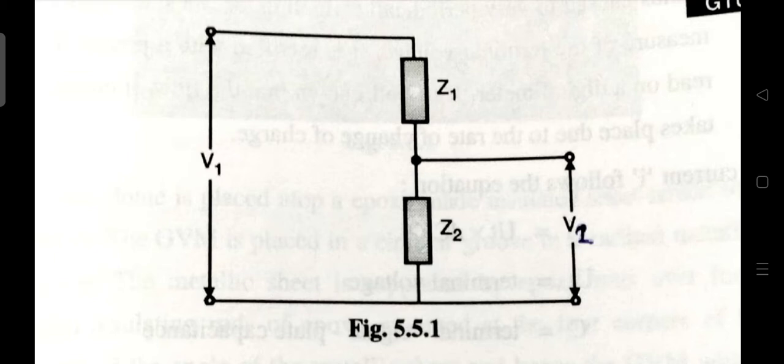The low resistance R2 or Z2 and the potential divider are connected as shown in this figure. Due to sudden changes in voltage caused by fast switching operations or flashover of test voltages or short circuit, flashover or damage may occur to the divider elements. This is due to stray capacitance across the elements.